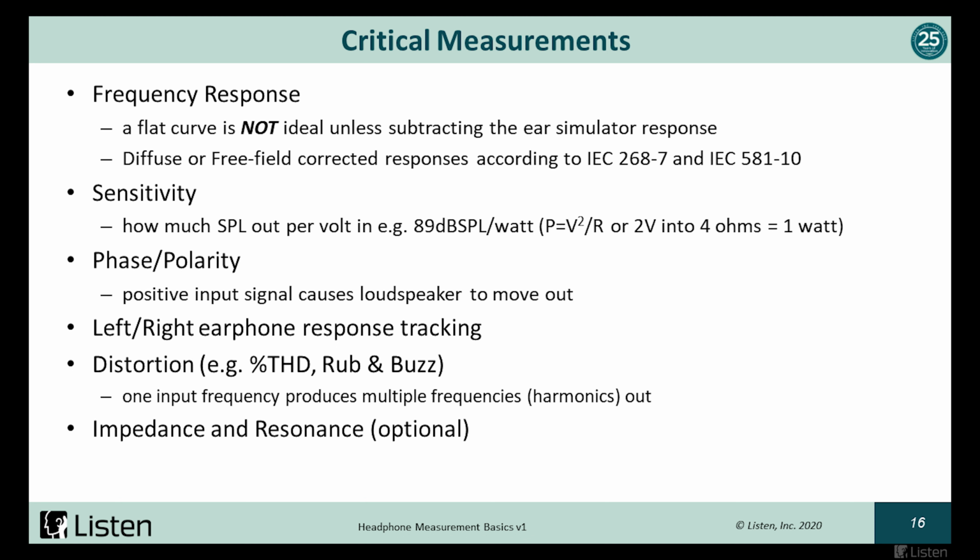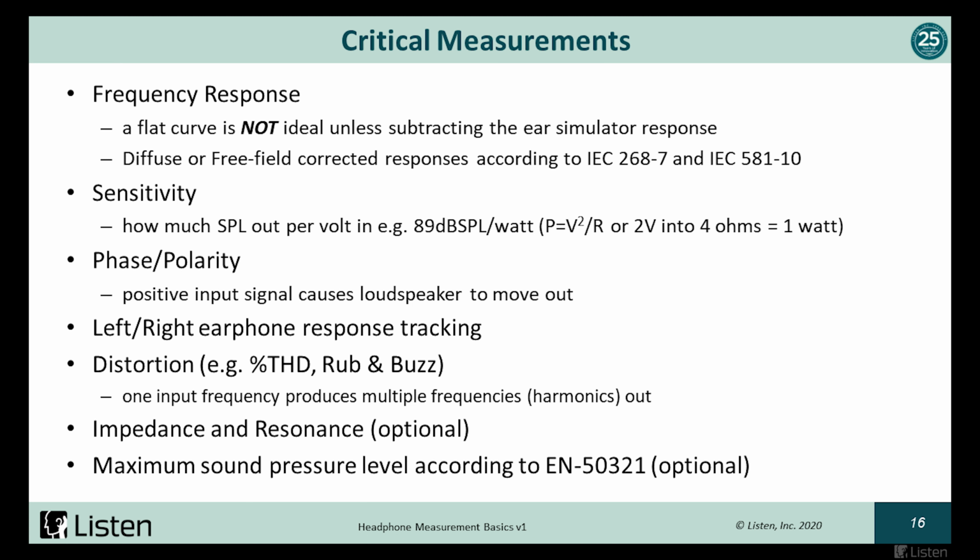I talked a little bit about impedance and resonance. Again, if you're measuring the raw transducer, this is important to know. Typically, the resonant frequency is much higher on the earphone than it is on a traditional loudspeaker. And you really want to be able to control that because it will break up. You get breakup modes in the headphones, which do become audible and typically fall closer to the most sensitive frequency range of human hearing. And then, as I mentioned before, headphones can play quite loud and damage your ears. And there is a standard I'll talk about as well for maximum sound pressure level.